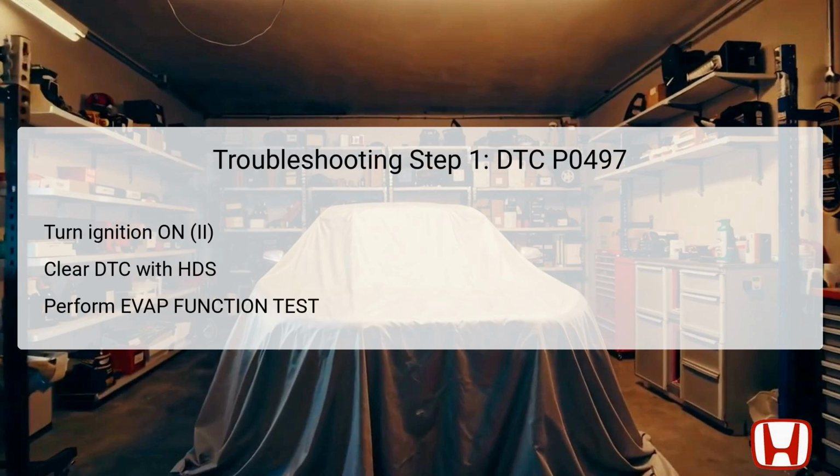The troubleshooting process begins with problem verification. First, turn the ignition switch to the on position, specifically to the II setting, which powers the vehicle's electrical systems without starting the engine. Then, use the Honda Diagnostic System, HDS, to clear the DTC, which resets the system and allows for fresh testing. Following that, you must perform the EVAP function test using the HDS. This test determines whether the system is operating correctly.